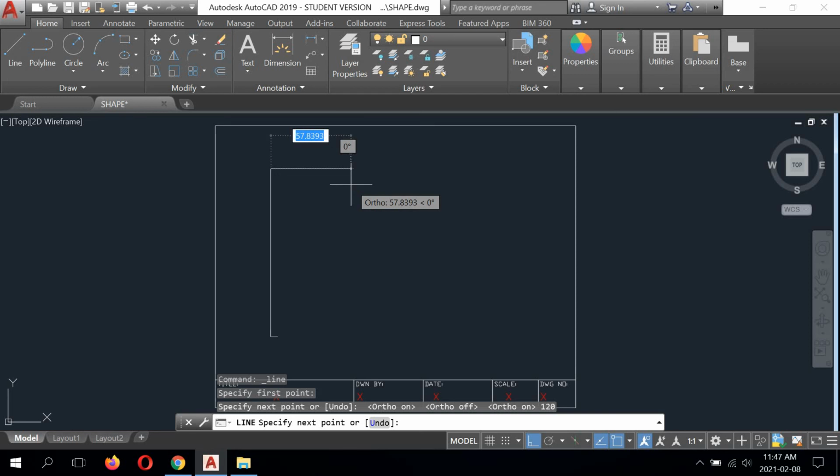When you're drawing lines, you don't want to look at the preview that you're getting. As I move the mouse back and forth, I'm getting these numbers highlighted in blue. Don't try to pinpoint it that way. You actually have to key in the value with the keyboard and then hit enter, and that will draw the line.